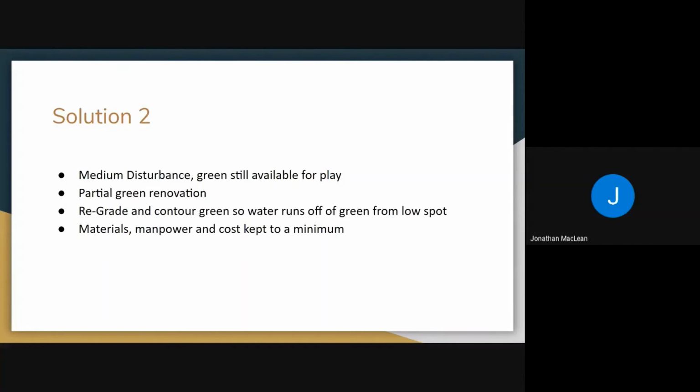When water is trapped and concentrated, the upper root zone will remain saturated for extended periods of time, and turf failure will ultimately occur due to anaerobic conditions. Increasing disease, algae, and black layer problems also are commonly experienced on putting greens with poor surface drainage. With this in mind, the low spot of the green where there is water pooling on the surface will be removed by means of regrading the section between the water and the green collar, allowing water to have a path to drain.